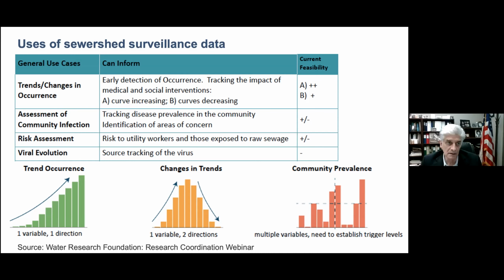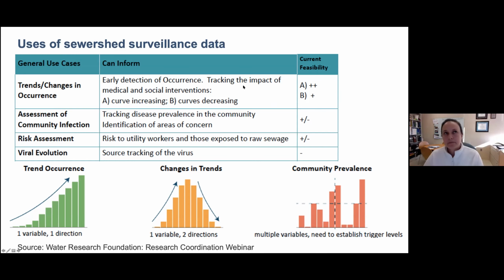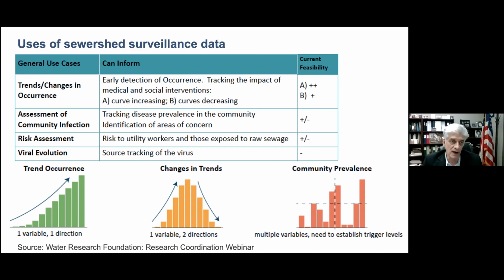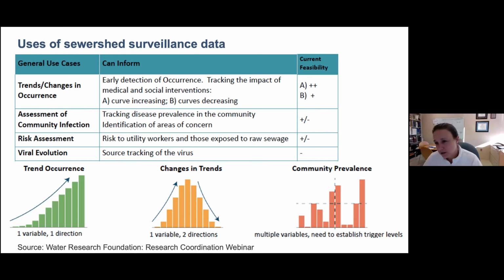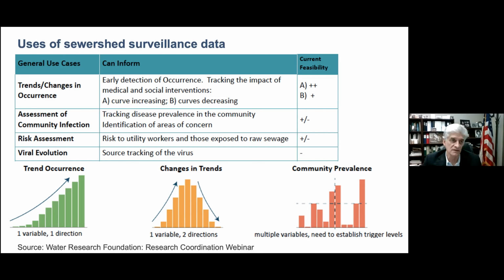Belinda, this is Gary Beard in Louisiana. Have any of your tests looked at the reduction or possible reduction of the virus through the treatment process itself? In other words, measured it in effluent prior to disinfection. I'm sure disinfection, especially with chlorination, takes care of most of that. So I initially did a few samples of effluent and they were all non-detect, as they should be. That was post-disinfection. Did you take any prior to disinfection?